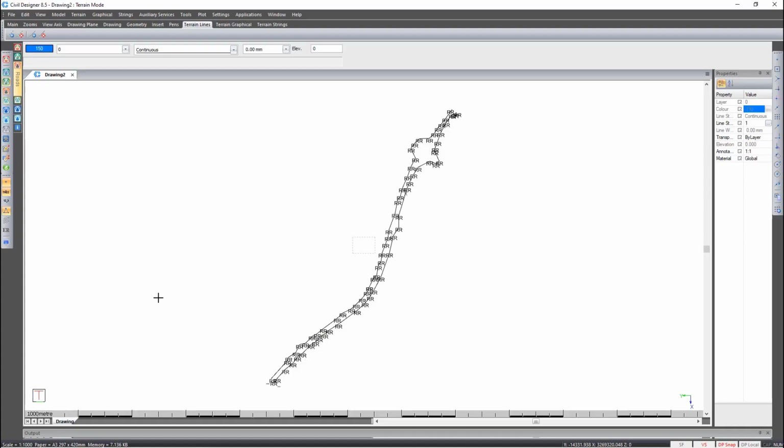Taking a closer look at what we want to achieve here. Eventually I'm going to go to the roads mode, go to signage, add linear road furniture, and in using this function you need to obtain a polyline, or alternatively you could design a road and then use the display line of the road. In our case we're going to use the polyline function.